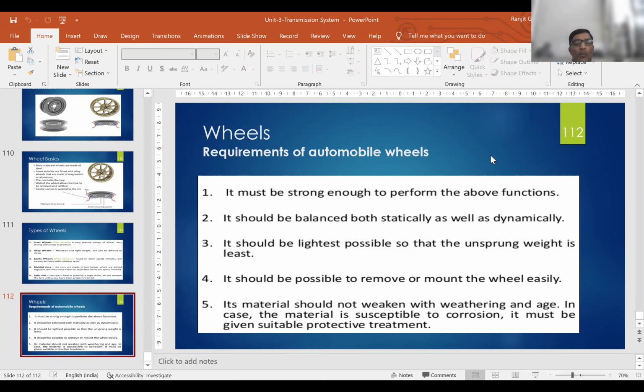Depending upon the type of steering, the components vary. But in all steering types, the steering gearbox is used, which is required to convert rotary motion into to and fro motion of the drag link or push and pull rod.